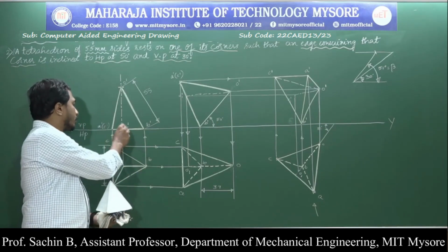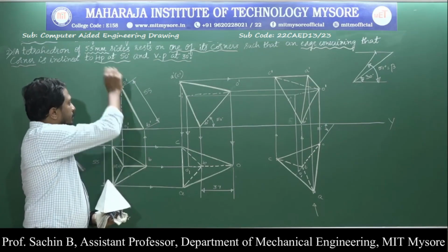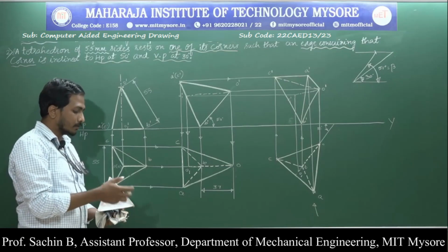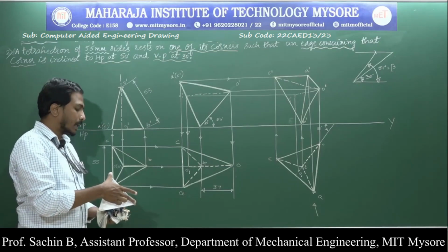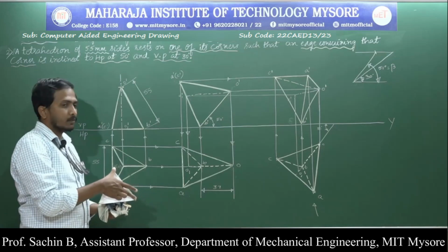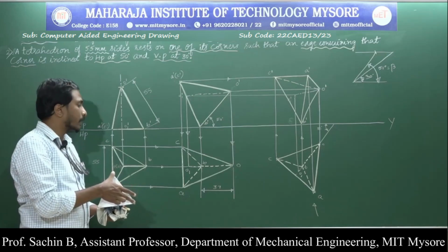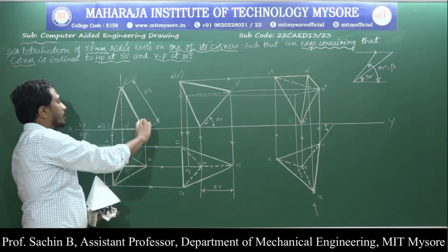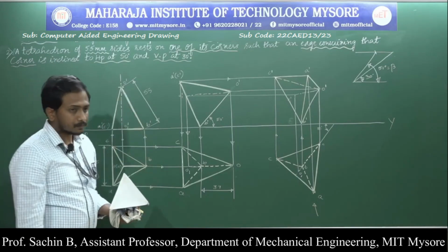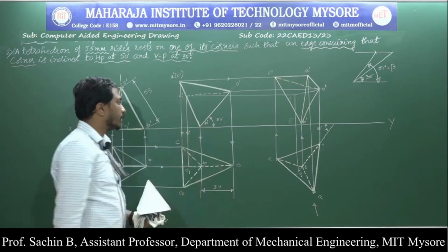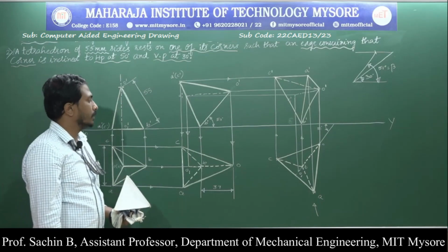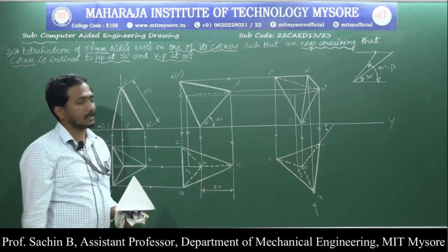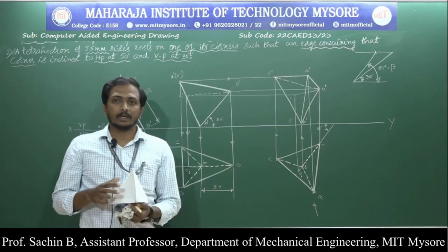Next, go for drawing the front view. While drawing the front view, first extend the axis. According to the concept and the view of the object, this slant edge, if I project it, is the only slant edge where the required length is available. After extending it, I am going to cut the R from the corner. Next, I am going to draw all the remaining edges. Next, I incline that object to 50 degrees by resting on the corner itself. I draw the top view. Again, the same thing in the last position. This is about the tetrahedron problem.